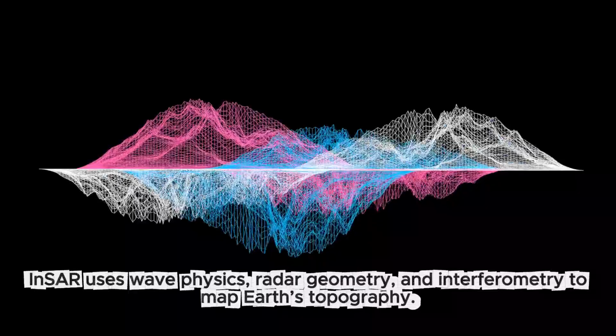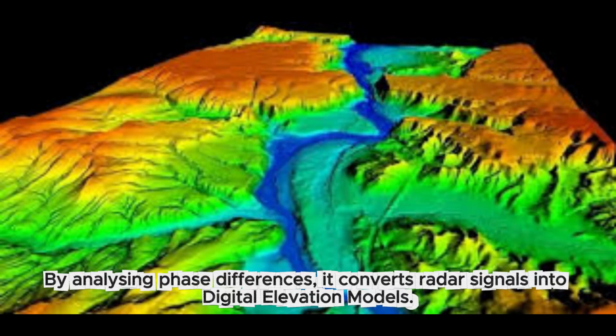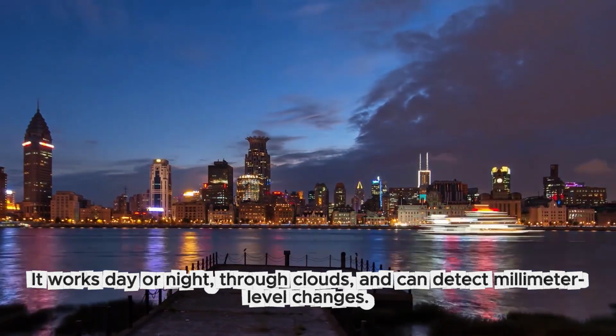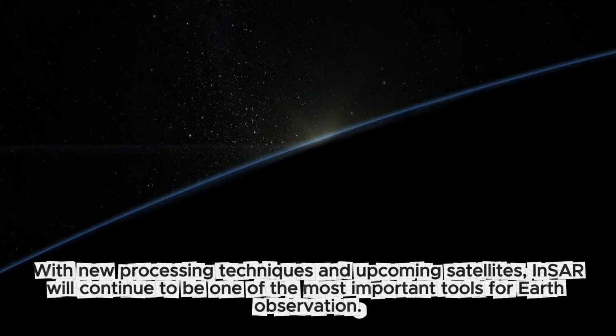InSAR uses wave physics, radar geometry, and interferometry to map Earth's topography. By analyzing phase differences, it converts radar signals into digital elevation models. It works day or night through clouds and can detect millimeter-level changes. With new processing techniques,